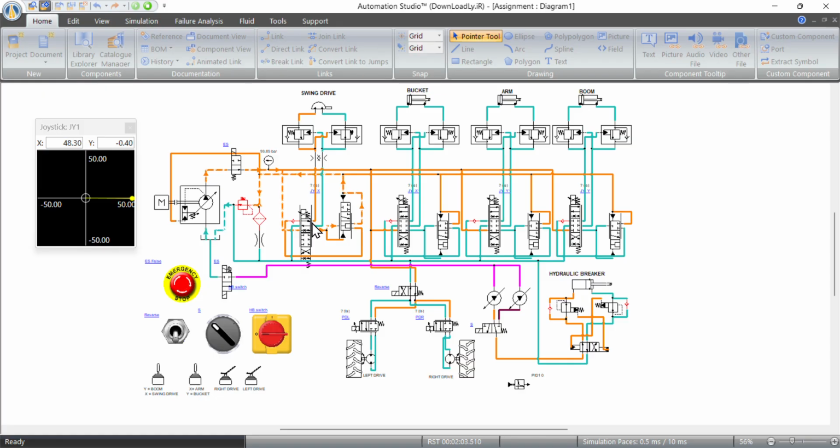After that, the fluid flows through the orifices, which restrict the flow rate of the fluid to slow down the movement of the rotary motor because it rotates in angle. The fluid will then pass through the check valve at the unloading valve with pivot at extension, which actuates the unloading valve at retraction, allowing the fluid to pass through the unloading valve and flow back to the reservoir. The rotary motor moves from right to left.